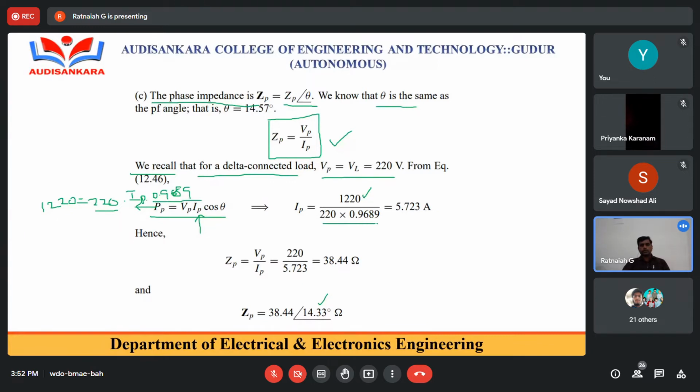So 220 into 0.9689 gives the current through the load, that is per phase of the load. That's the phase current. So the phase current is 5.723 amperes. Now what is the per phase impedance? If you know the value of V phase and I phase, then the per phase impedance is 38.44 ohms. That is 220 divided by this phase current 5.723, I can get 38.44 ohms.